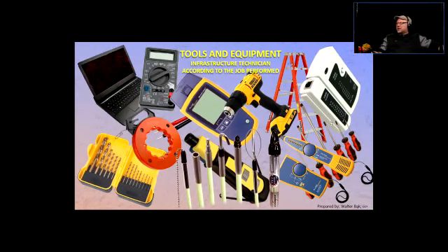Now, as far as diagnostic equipment, also here is the toner, right here. The toner consists of a tone generator and a probe. A tone generator will, besides other things, test for continuity. Every little company has slightly different ways of doing those. But basically, the main reason for having that is to be able to inject a tone into a pair.